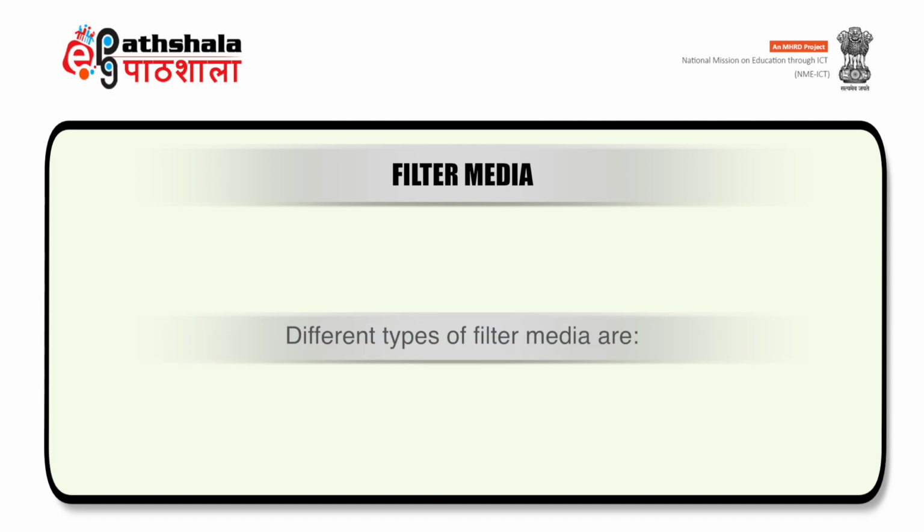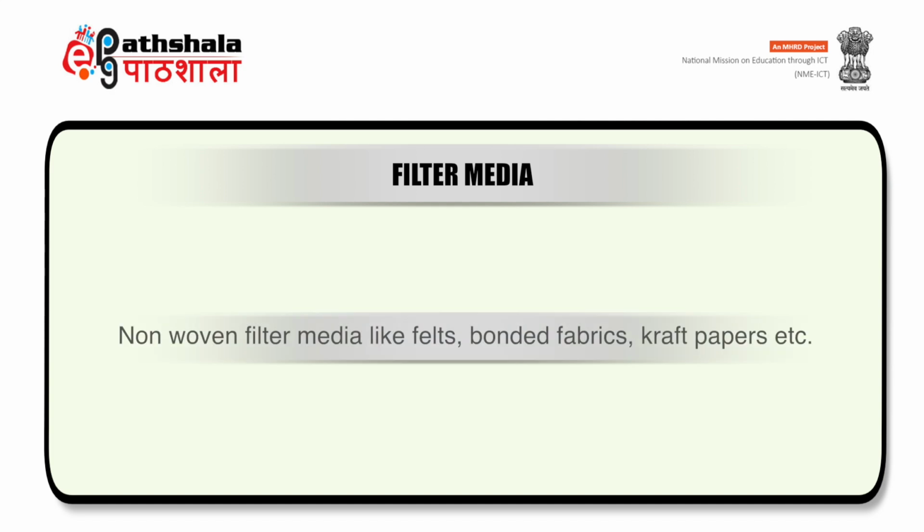Different types of filter media are: first, filter cloth like cotton, nylon, Teflon. Second, woven wire cloth like stainless steel meshwork. Third, non-woven filter media like felts, bonded fabric, kraft papers, etc.